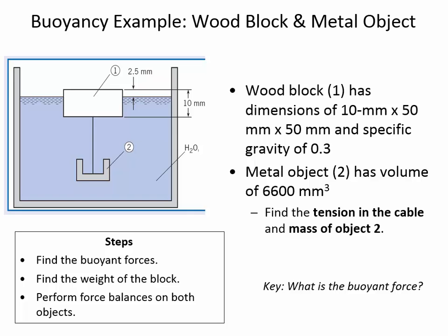That is going to equal the weight of concrete. And the weight also depends on the volume of this block, whatever it is. Instead of saying volume displaced, I'm going to say the volume of the block, because it's this concrete block that's displacing the water. And then it is going to be the unit weight of the block.